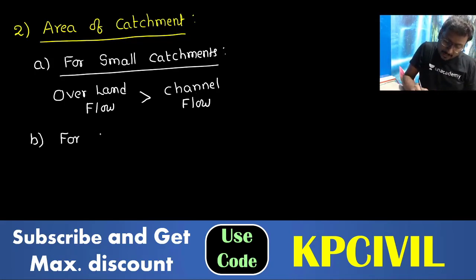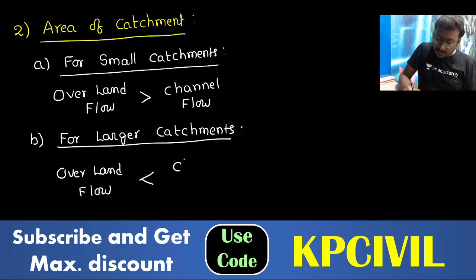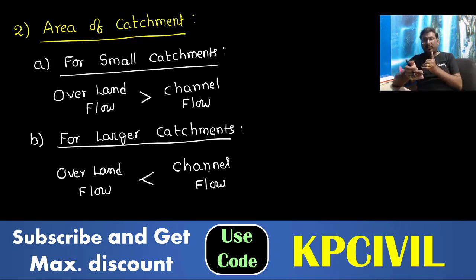For larger catchments, there is a huge area open to the atmosphere, and precipitation is falling down. So what happened? For larger catchments, overland flow is less because it takes a long time to reach. But with direct fall of precipitation, channel flow is high. Channel flow is greater than overland flow. Or you can write, overland flow is less than channel flow.